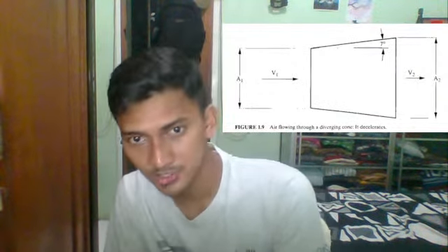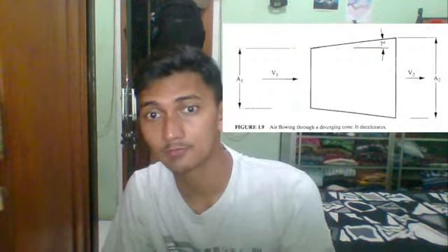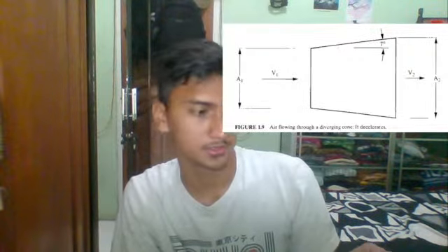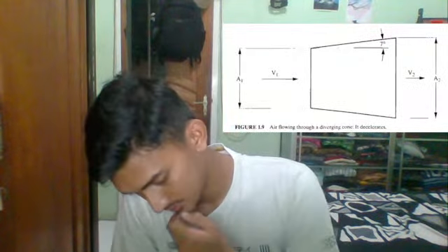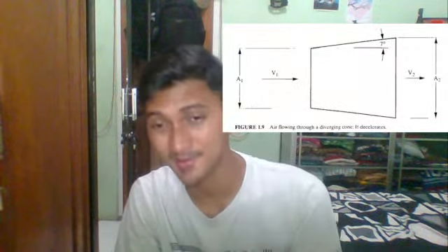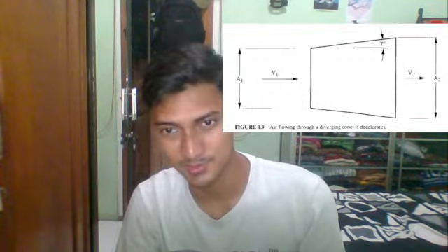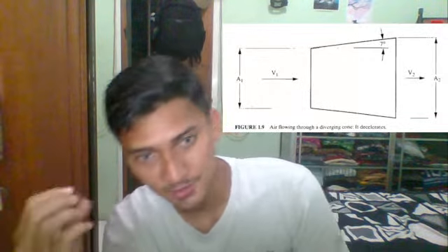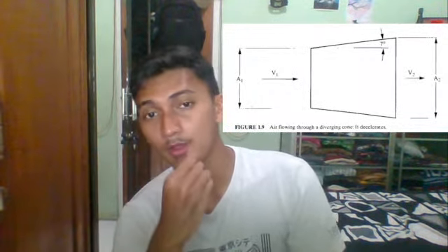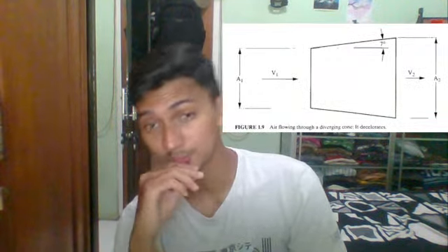Using the same dimension, the same airflow as in the figure before on the converging example with a number. The velocity pressure now will decrease from 1.57 to 0.50 in water column, right?